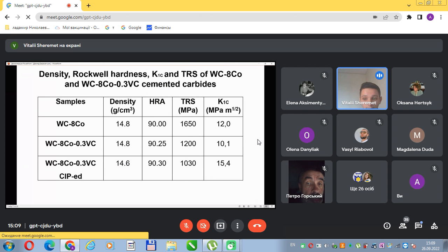of alloys. As is well known, the hardness value of cemented carbides is a function of the grain size according to the Hall-Petch relation, the Hall-Petch equation. As the tungsten carbide grain size becomes thinner, the hardness of the cemented carbides increases. The results indicate that the hardness increases slightly as the tungsten carbide grain size decreases.